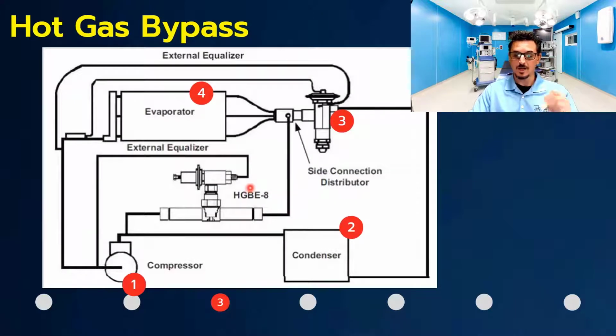I show this slide because a lot of people get confused between hot gas bypass and hot gas reheat. They might think that if I have a 5-ton unit with hot gas bypass, then I could control and modulate over all load conditions, and that's not really true.